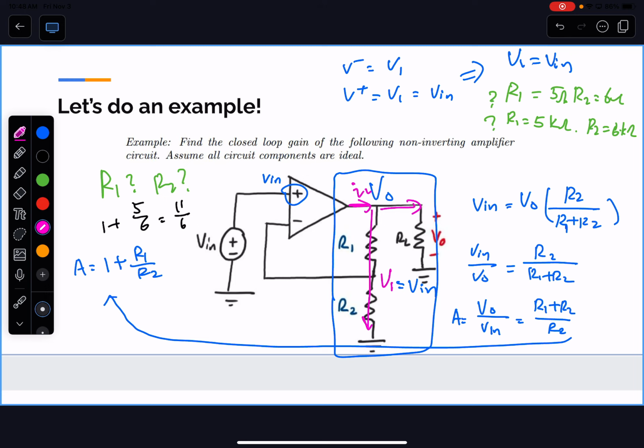What if I put, let's say, 5,000 ohms of something like a light bulb? You have 10 ohms of resistance here, and you have 5,000 on the other side, and the electrons coming out of the port are like, I'm going to take the path of least resistance. I'm going to go through the 10 ohms completely, leaving nothing going through the 5,000. Yes, you got your control signal, but it doesn't do anything at that point. It's wasted. It's all sent to the ground for nothing. So you want to have high resistance, so you can get that voltage but preserve the current for other use.